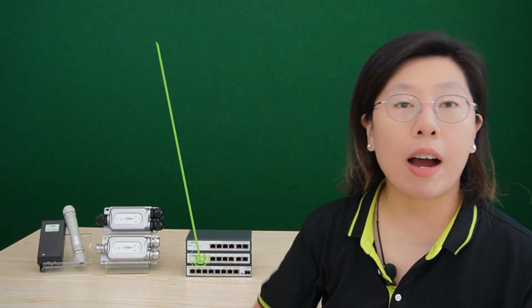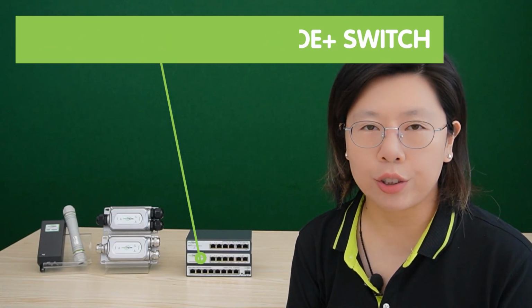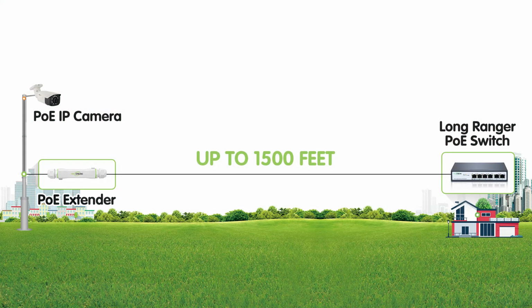Beneath it, we have our 4-port long-range PoE switch. It has a PoE power extender feature to break maximum PoE distance for IP devices, requiring a continuous Ethernet run of 1,500 feet, and also a maximum of 500-meter Ethernet cable or PoE connection between the long-range PoE switch and the PDs, such as PoE camera. It is also compatible with the IEEE 802.3 AF and AT standard, supports PoE and PoE Plus, and supplies up to 30 watts of power output per port.